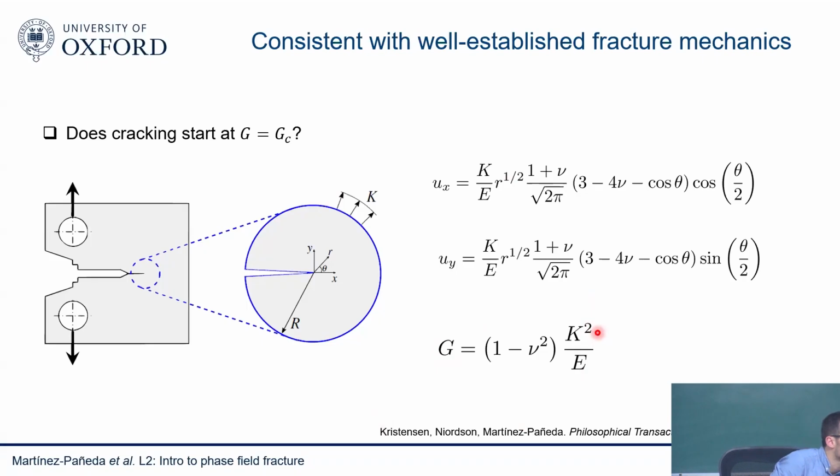When you keep on increasing, the K field is not applicable on some sides. That's correct, so what we discussed before, if you have, here I'm just looking at linear elasticity, so it will always be applicable. If you have an elastoplastic material, you could have some edge effects, I guess, depending on the size of the sample. If you have an elastoplastic material, eventually the plastic zone will be so large that your K field will become invalid. What about the first terms of the infinite series of the Westergaard? Yes, so you have a T stress and other things as well. You could actually add them if you wish to. You could have a constraint effect, for example, with a T stress and so on. But in principle, this is the dominant term, yes, of the Westergaard series.